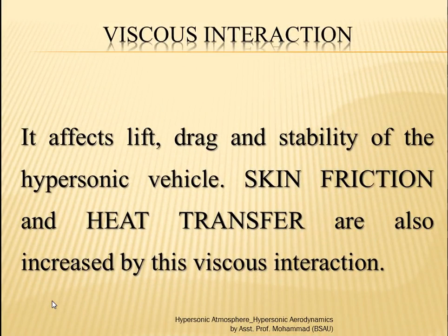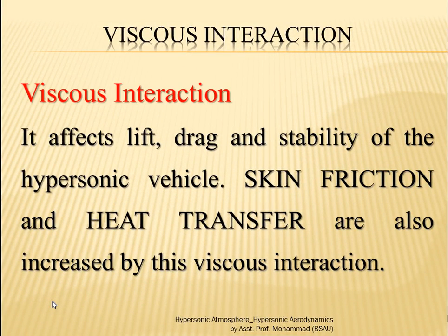Hence, the lift, drag and stability of the hypersonic vehicle, even the skin friction drag and the heat transfer, all are affected. It's not just that they are interacting and they pose a problem to the analysis. They affect everything. So whatever analysis people have done depending upon high speed flow in the supersonic regime, that is completely ruptured because of this viscous interaction.